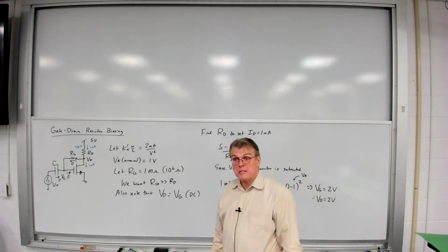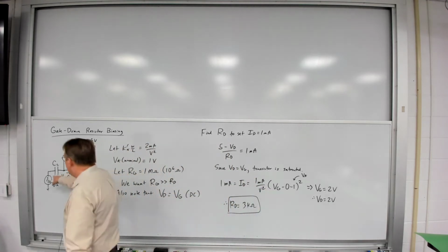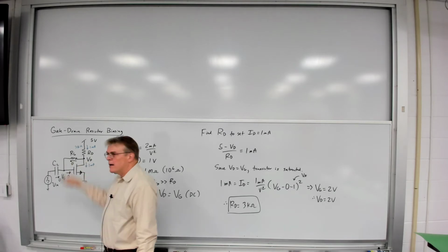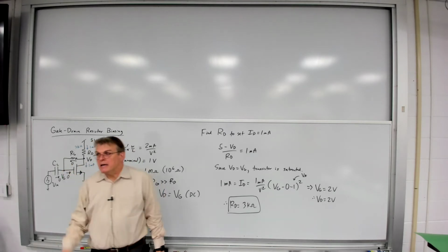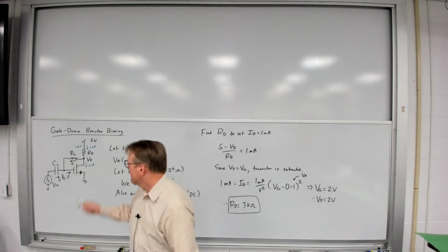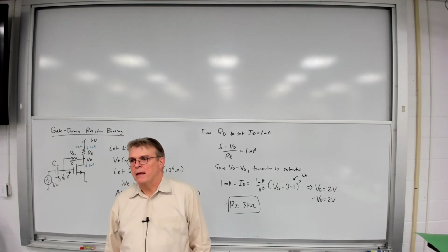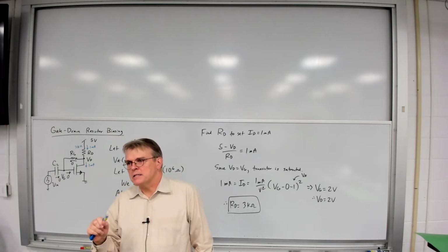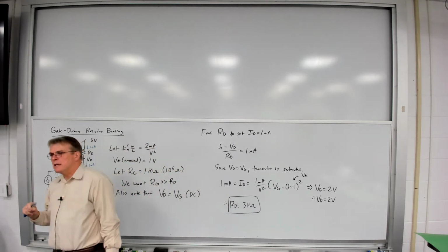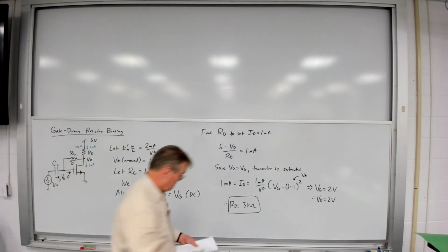It actually works as an amplifier because the transistor is in saturation. I've got a coupling capacitor. I can feed the signal into the gate, and in effect, this becomes a common source topology, a simple common source topology, with the addition, of course, of that RG resistor you have to include in the small signal diagram. But the question is how well does this topology work when you consider delta VT variations?